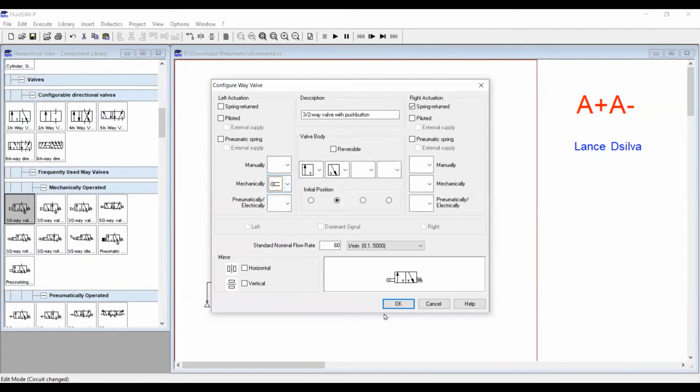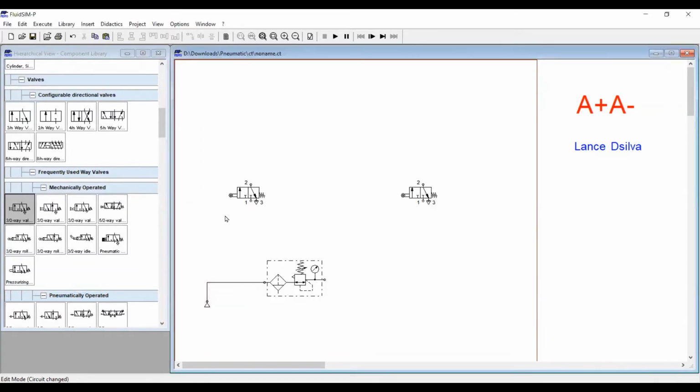Now we have to connect it to this, because it requires the air pressure, right? It requires the compressed air, so we connect this over here. Now click on the line. If you want to take it down somewhere, you can do it via the mouse, but sometimes it's not the best thing because there are some other lines going through and it becomes very hasty. So just click on it here and drag to this point so it gets connected, right?